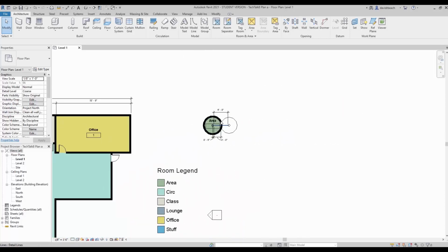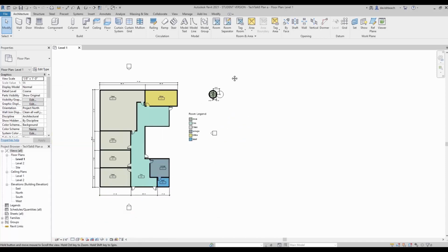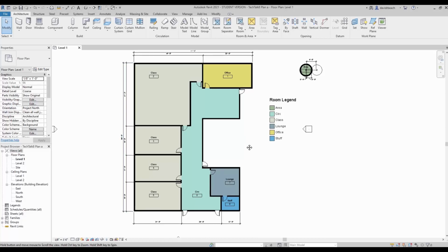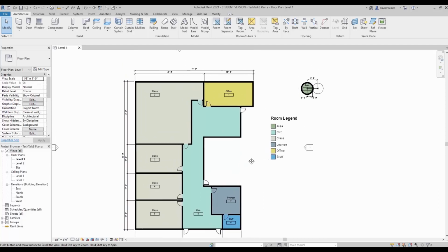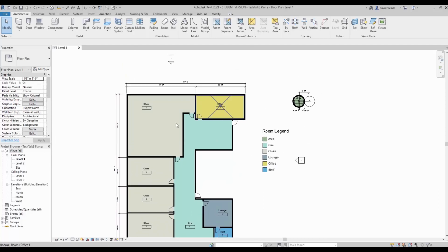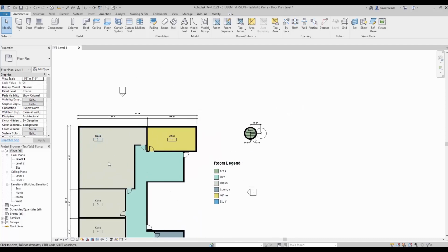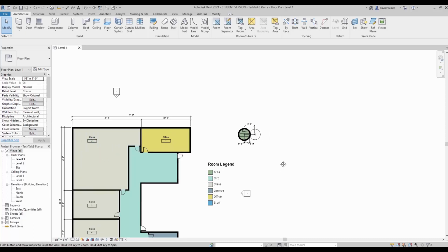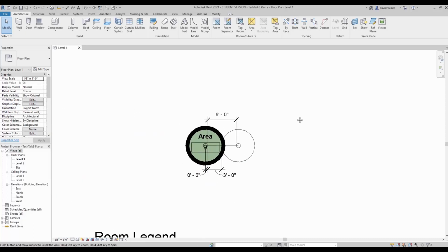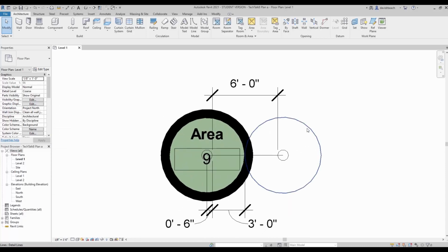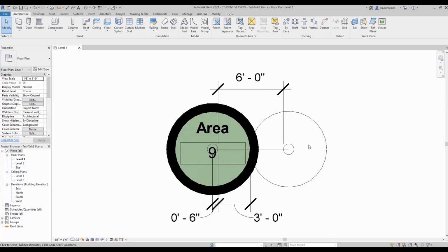So let's start really quick by looking at, well, let's just reference this really quick. This is a terrible floor plan I just generated for reference just so we could run these things through a test really quickly. And we're going to use Dynamo to calculate this. So it updates dynamically, and we'll look at bringing those occupancy loads directly into our floor plan as well, pushed in from Dynamo.